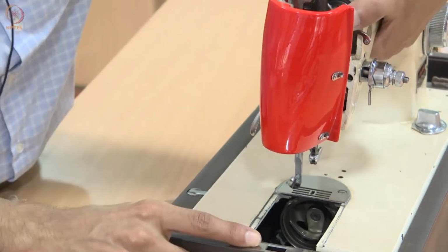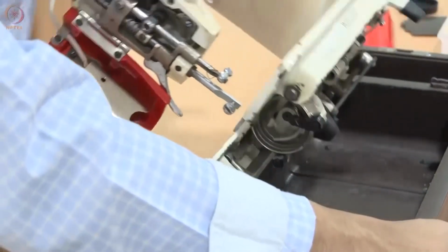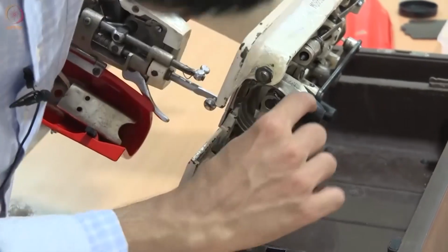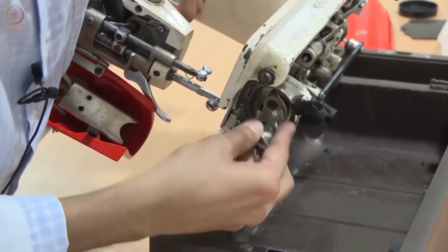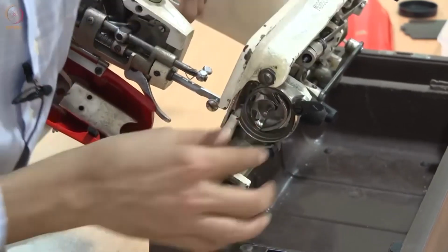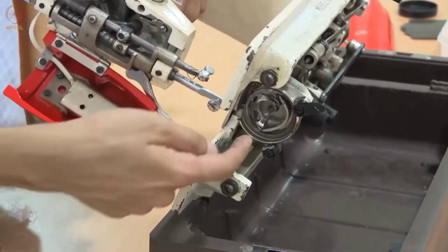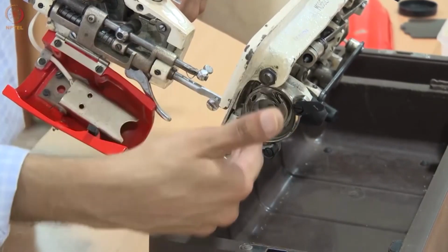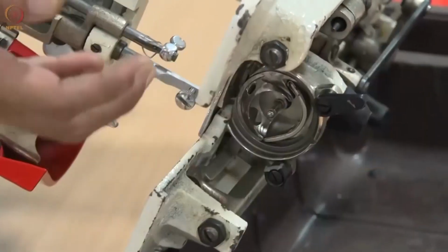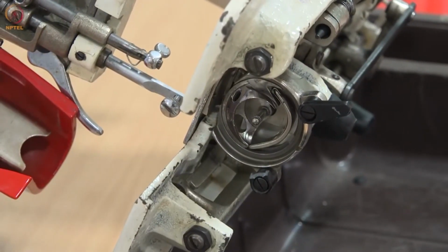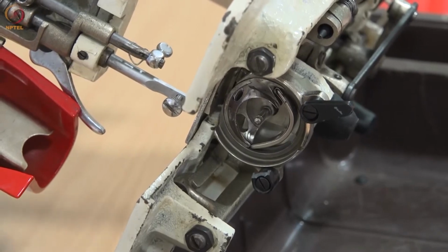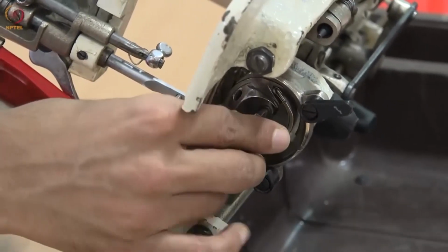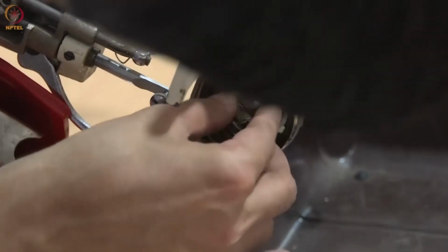Let me show you how this is assembled at the bottom. This goes inside like this. We remove this lever, one is broken. Now, some machines will have this construction in this way. Some machines, Singer, will have this entire bobbin facing this way, that is 90 degrees. This entire mechanism will be rotated 90 degrees. That depends on the manufacturer. Once you load the spool, you put it inside like so.